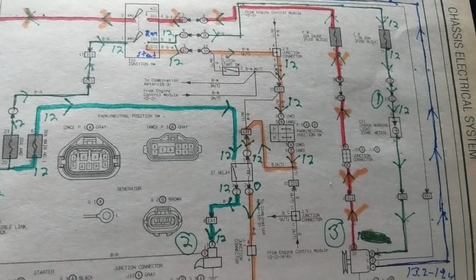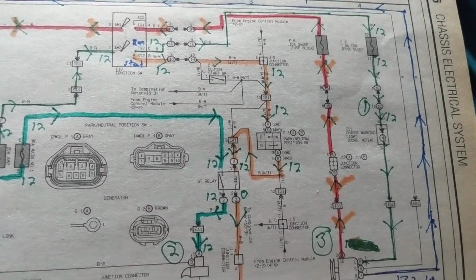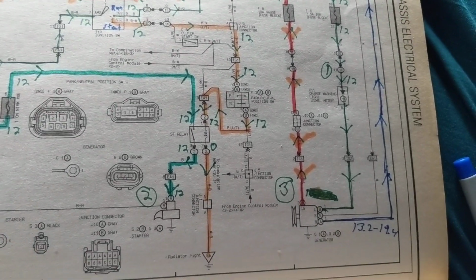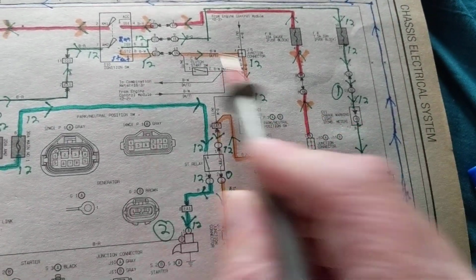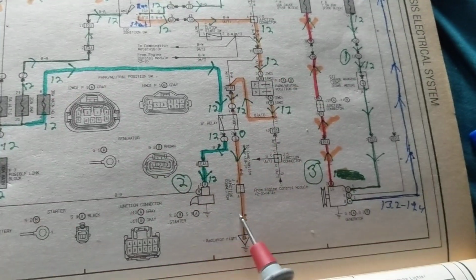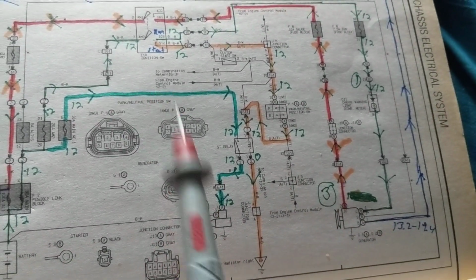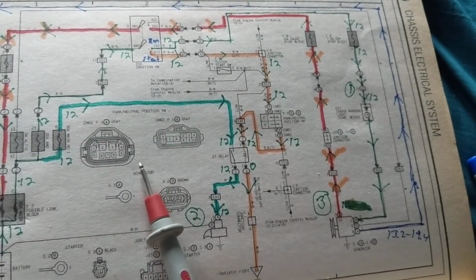If your battery voltage is not 12 volts when I'm in the run position, and I look at it and it's 10.5 volts, use that as an indicator that my problem is not here with the fuses and with the starter motor. My problem is first to get that battery charged to 12 volts or 12.6 volts.